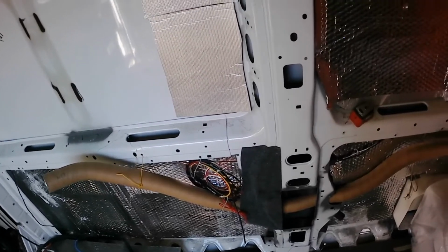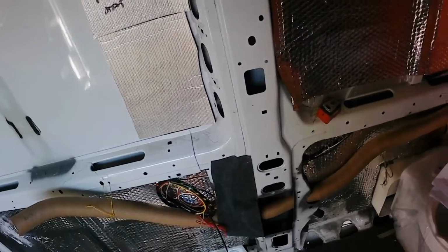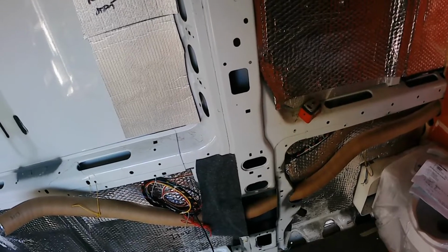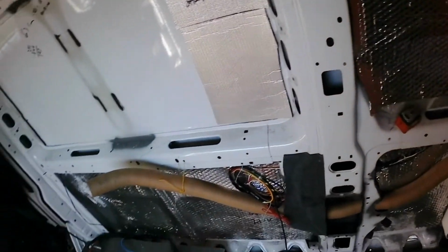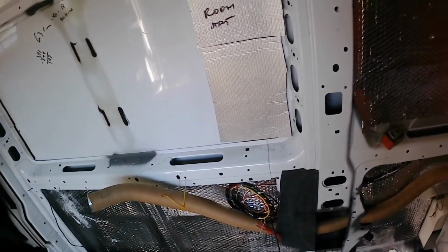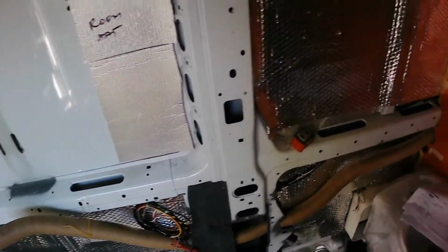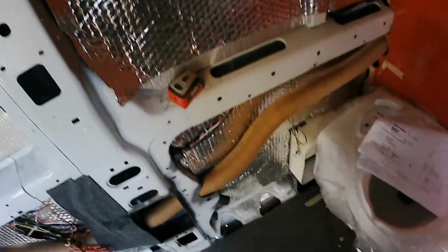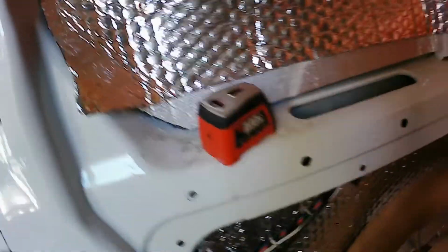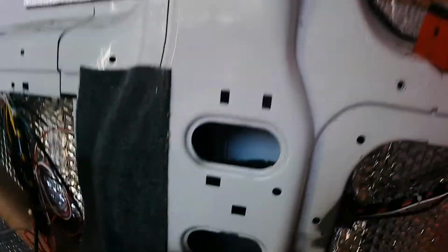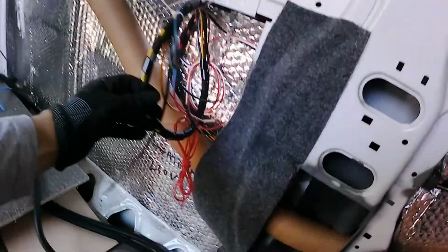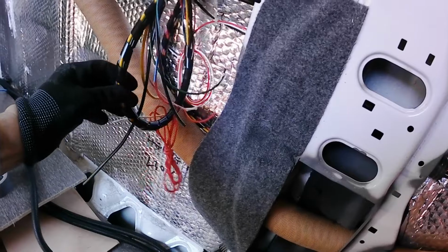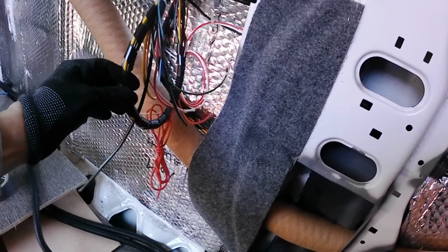To tell the truth, when we start building a camper van or change the wiring in a motorhome, we can think about wiring for lights. This is quite simple, we can calculate it, and usually it is always flat twin 1.5 and will be more than enough.